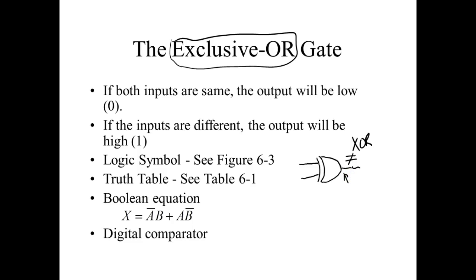So if I was going to draw a truth table, and I call the inputs A, B, these guys will only have 4 entries in a truth table because they only have 2 inputs. No more, no less. There is not a negated symbol. There is not a negative symbol for an exclusive OR gate. So that push and bubble things we talked about only applies to the 5 basic gates. There's no such thing as a negative exclusive NOR or an exclusive OR.